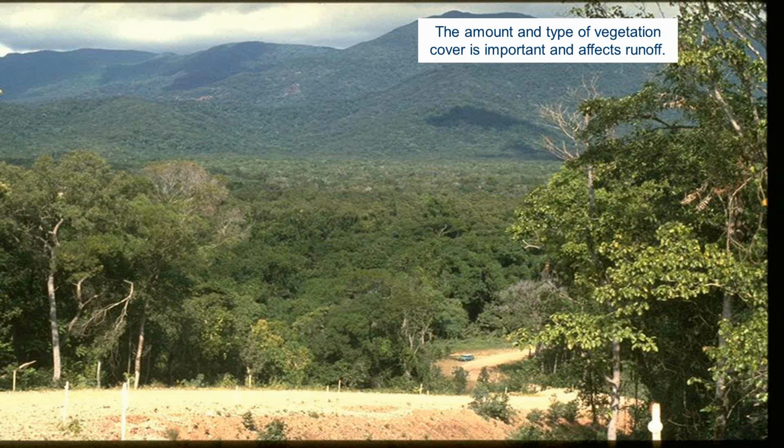And just on that point, one of the key elements we see as an engineer in this photo is a discrete variation in surface roughness, obviously in the form of Manning's n from an engineering perspective. On the gravel road in the foreground we might expect Manning's value to be as low as 0.02, reaching up to quite high values as we get into the upper reaches of that slope, where the Manning's value may rise to 0.15 or greater.